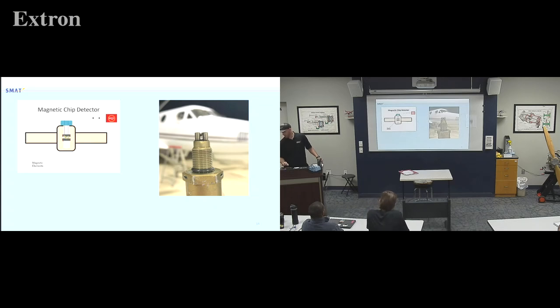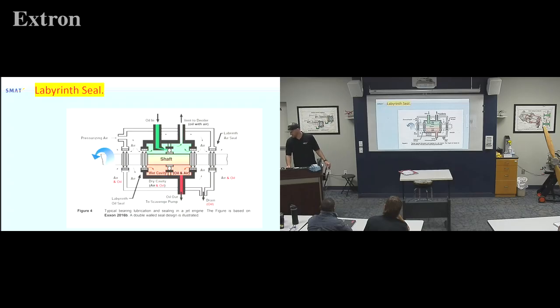That one Prepware question says a small amount of gray fuzziness is considered normal wear. So remember that, a small amount of gray fuzziness, normal wear. You've got to get up to a certain size before we start worrying. Now, if you can see with the naked eye, those are like grains of sand and metal, it's not just fuzziness, you probably have a problem. But gray fuzziness, normal.